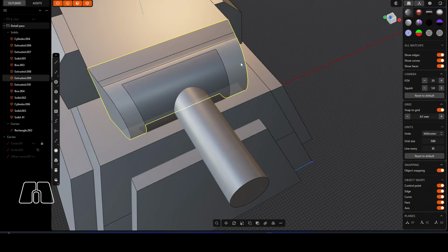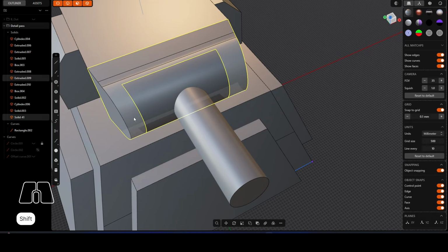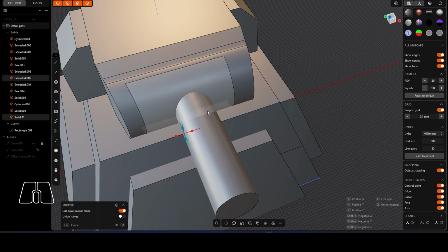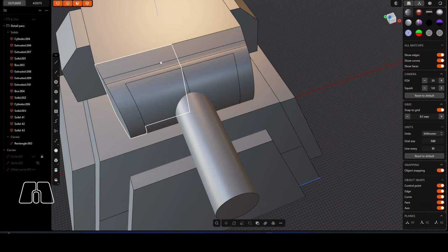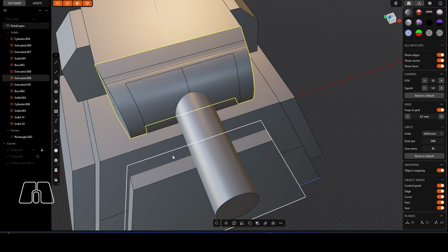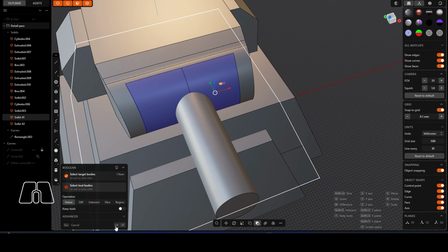What we need to do is mirror this across now, okay? So what we're going to do is grab each part here. I'm going to use the mirror, all right? Should be that side. And then we can click OK there. I've not merged them because I had both selected. So I'm just going to do a quick select union here. Grab this piece as well. Let's use Q, do a union.